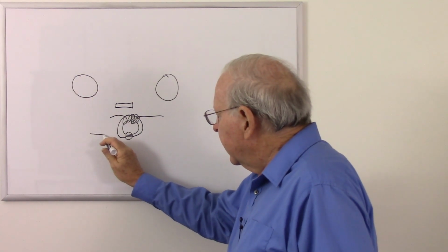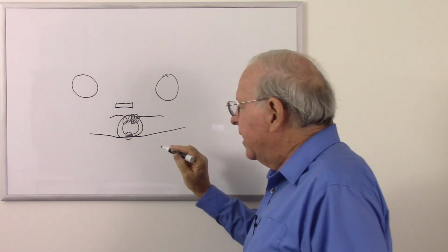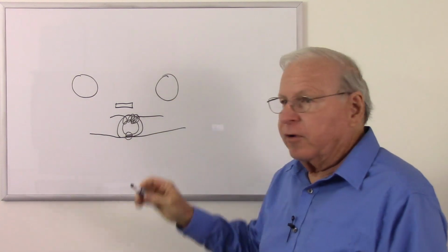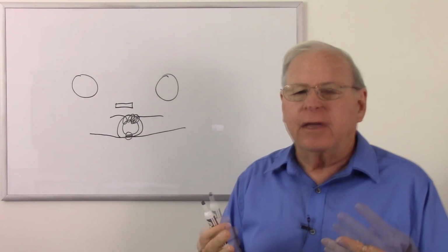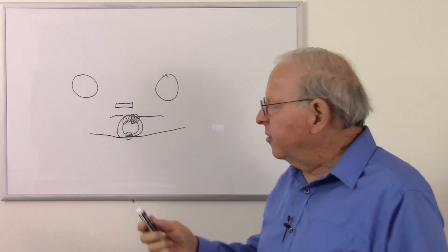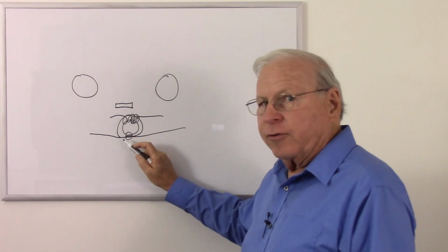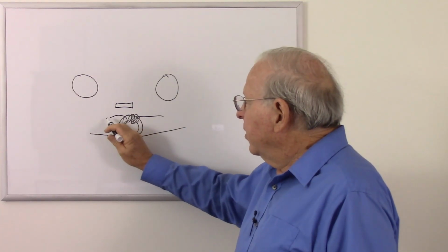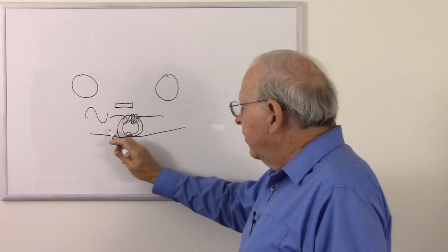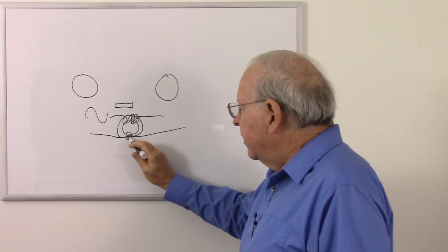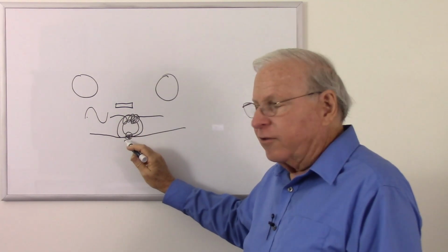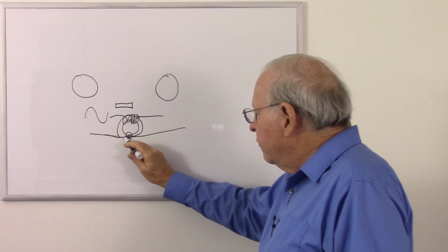All we need to do is get that wire to go across that gap, and that's going to expose the wire to the magnetic field and magnetize the wire, assuming that it's a proper alloy that will hold its magnetism once it's passed through a magnetic field. So we simply send our signal into there, and as the current gets higher, we get a stronger magnetic field here. As the current gets lower, that gets weaker. And all that time we are moving this tape by.